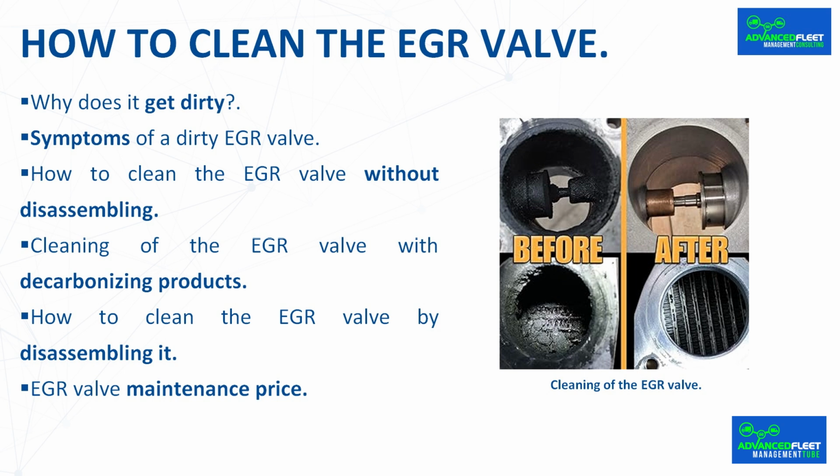Symptoms of a dirty EGR valve: engine shuddering and erratic operation, increased fuel consumption, dark exhaust smoke on acceleration, reduced engine power, especially when starting, and increased pollutant emissions.